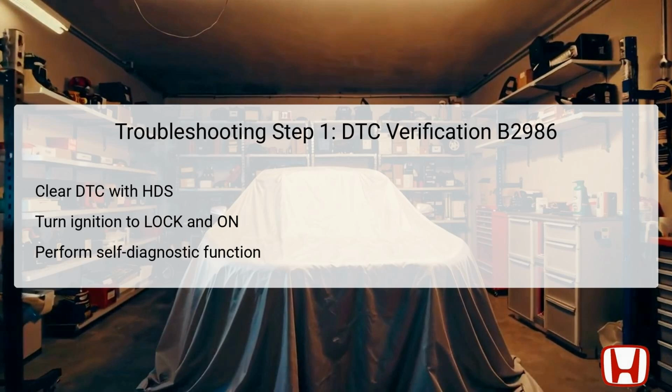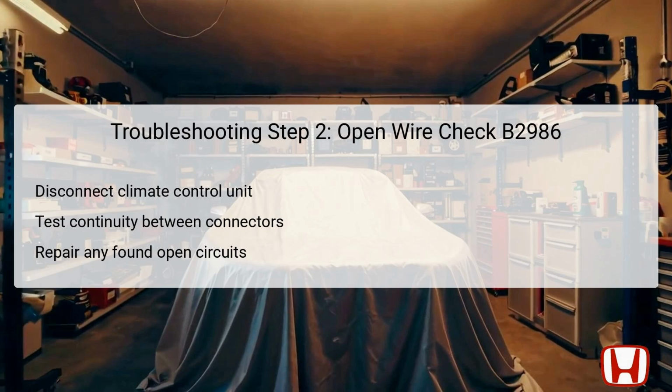After doing this, perform a self-diagnostic function through the HDS or the climate control unit to ascertain if the DTC reappears. If DTC B2986 is indicated again, you can proceed to the next step in the troubleshooting guide. If not, this could indicate an intermittent failure, drawing attention to potential loose wires or poor connections in the recirculation control motor circuit.